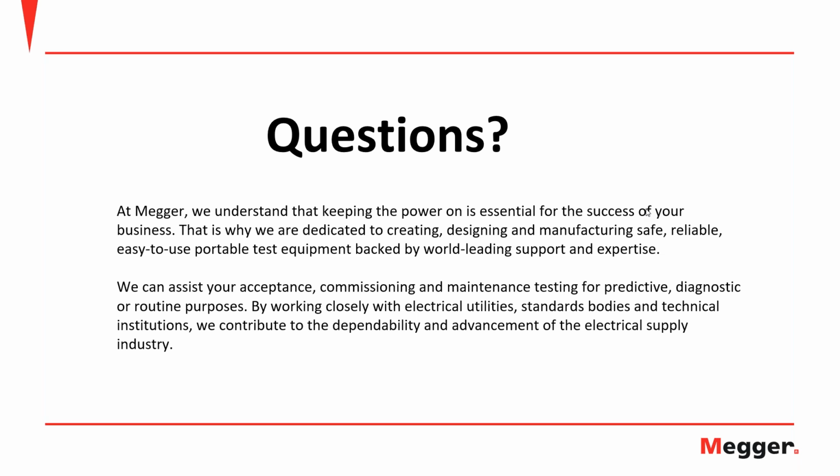Okay, I'm a little bit puzzled with this question because the actual electrode gap is different for 1816 and 877. So for 1816, it states that you can actually perform the test at 2 millimeters. However, if you don't achieve a breakdown, you then reduce the electrode gap to 1 millimeter. For 877, the electrode gap is 2.54 millimeters. So they're different gap settings altogether.